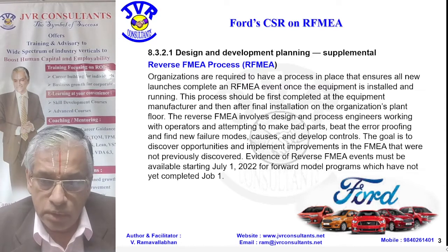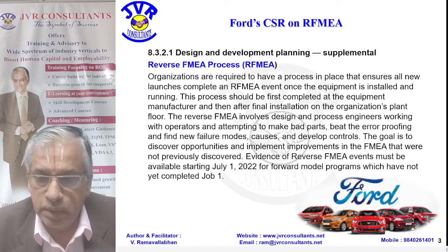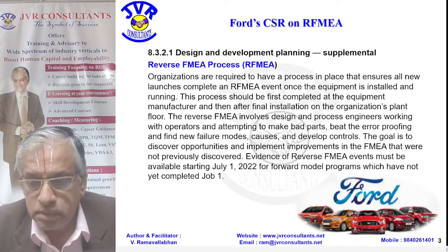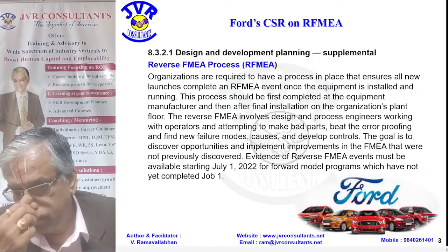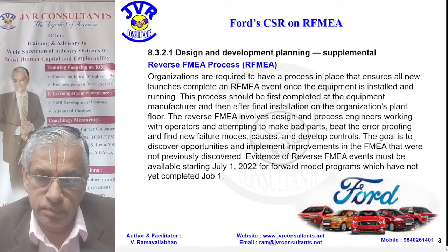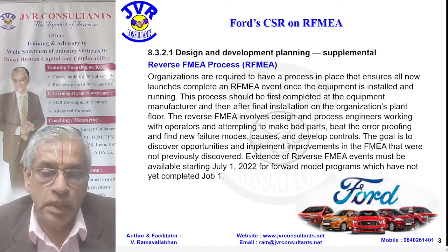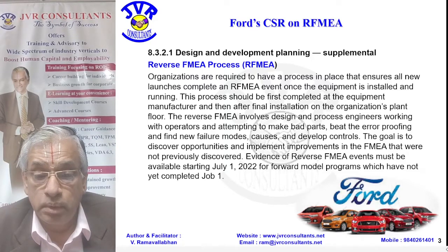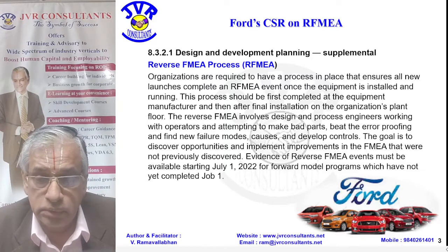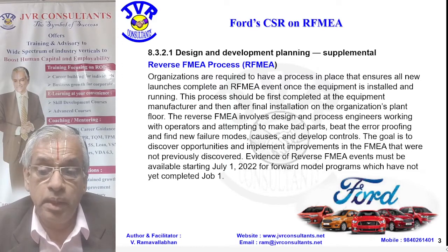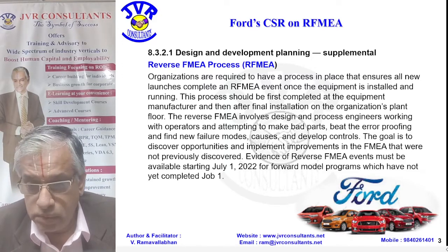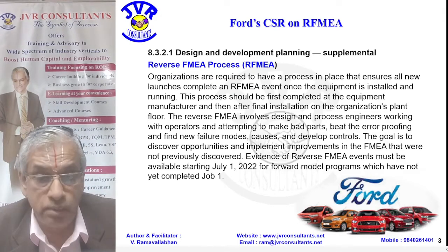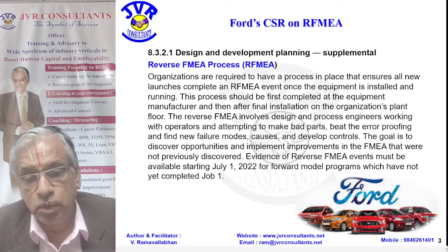Try to make some bad parts, pass them through the error proofing mechanism you have installed, and see whether your error proofing is catching or not. If that doesn't catch, there is a problem. Or when you are doing this exercise, you will come across some new failure modes and causes also. When you identify some new failure modes or causes, naturally you will start developing some controls also. We need to develop some controls anyway. So this is the whole idea.